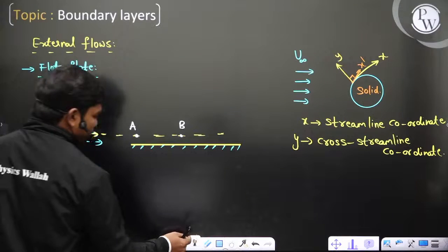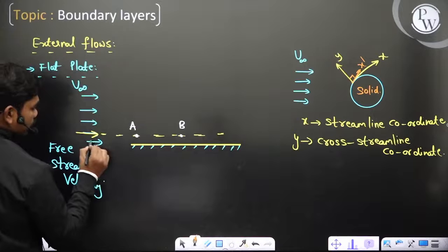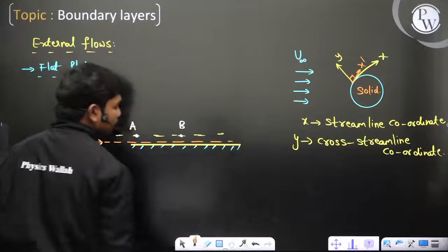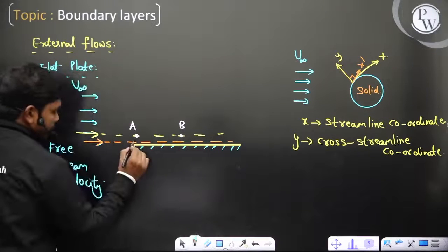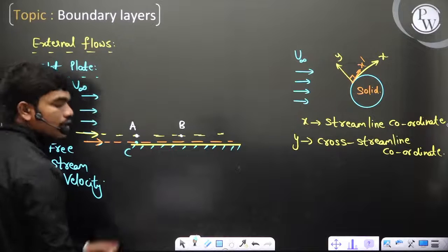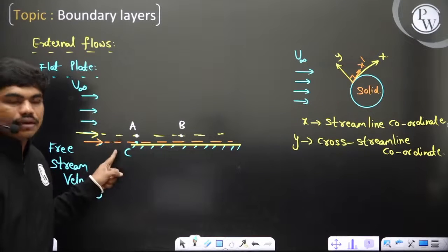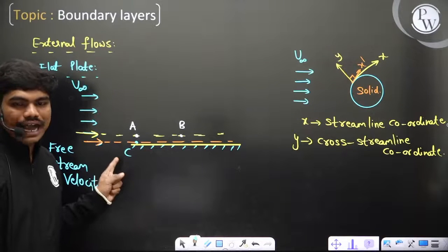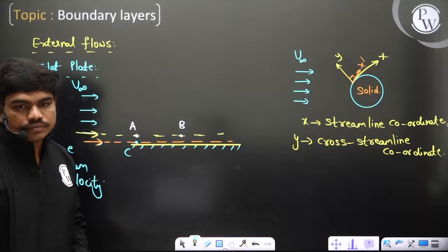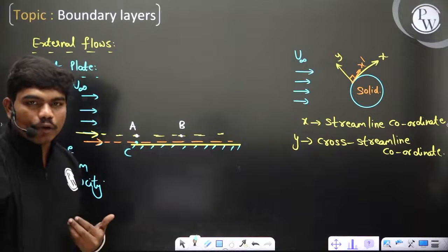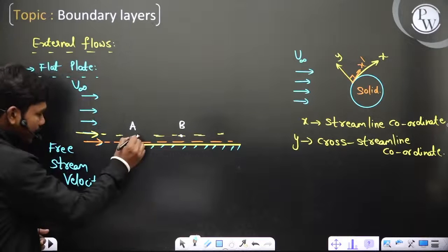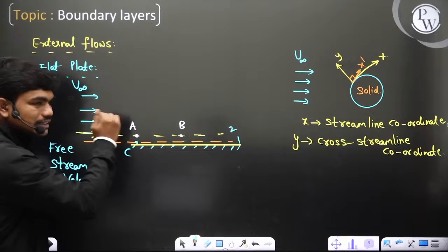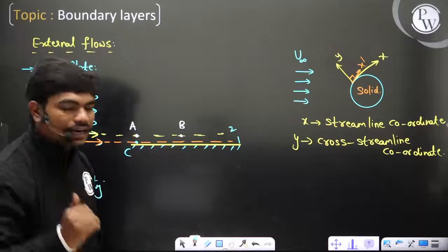Also, I want you to consider one more thing. If you take a different layer of fluid which is very close to this plate, and you take these 2 points A and C, which point has higher velocity? Can anyone tell me? Again, it's point A, correct? Point A has higher velocity because, compared to the second layer which I have marked in yellow, if I call this the first layer and that the second layer, the second layer will experience slightly less impact of the plate.